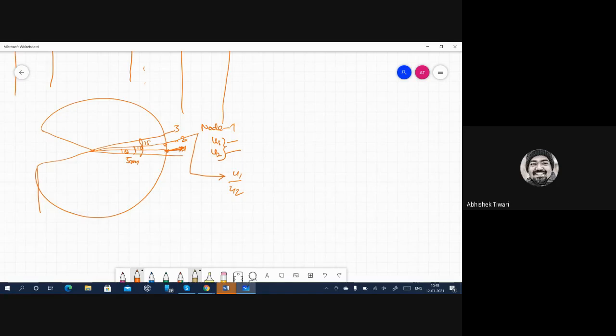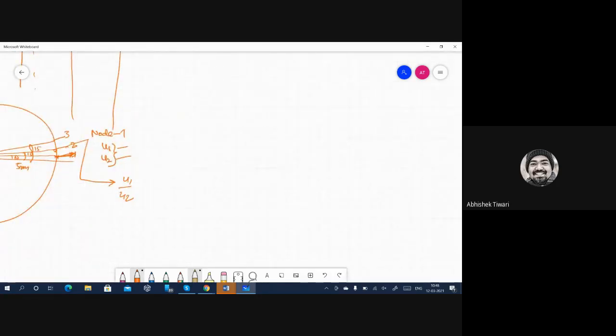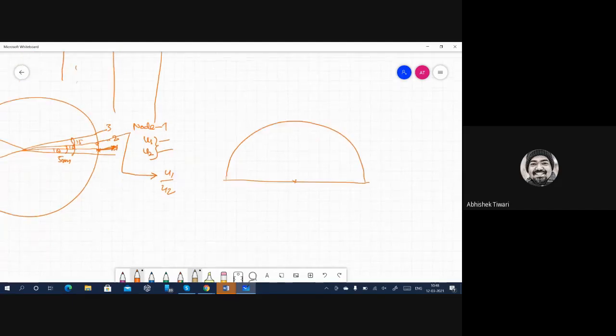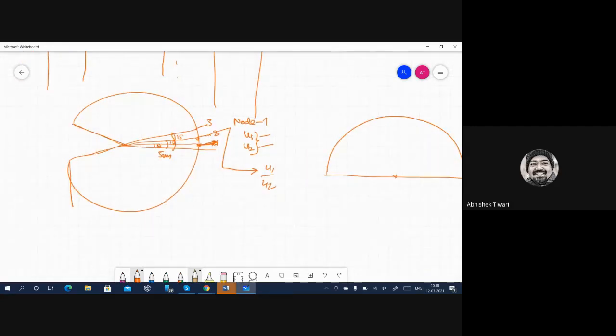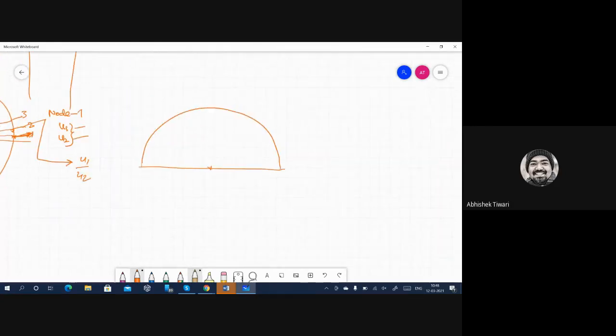There is no other boundary condition you have to apply, but you can be very much simpler. You can actually model a half circle. Remember, our crack is very sharp, so we will not model this kind of crescent thing. We will model the half and apply Y symmetry on these nodes, or whatever axis it is. So if this is X, this is Y, then you have to apply Y symmetry here.